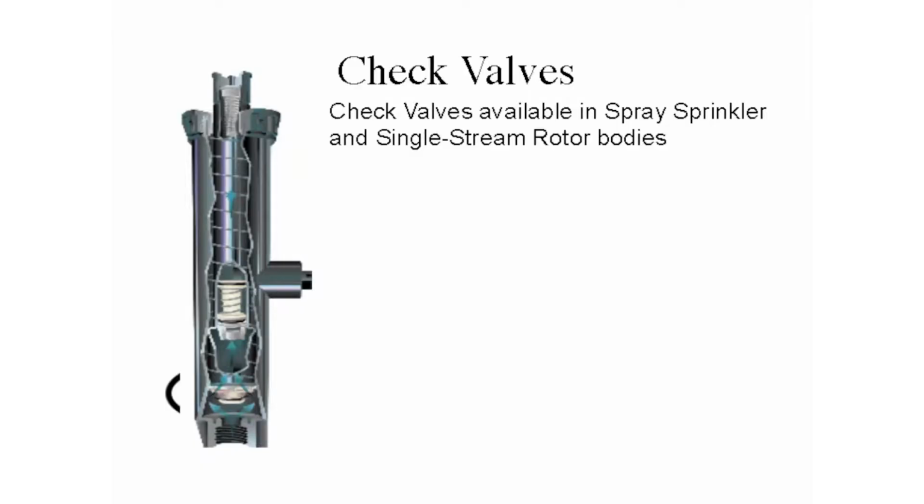And what we can do to prevent that is putting in a check valve. Let me show it to you. A check valve in the bottom of the sprinkler. I will pass these around in just a minute because I want to talk about two features. But this then keeps the water in the pipes, and you don't get that drooling. And that's something you can all do. If you can change a light bulb, you can change out to these features.